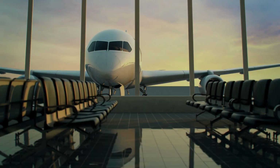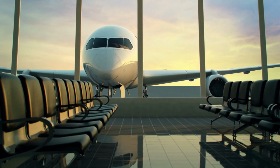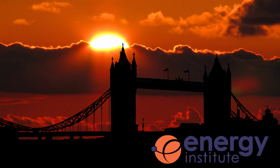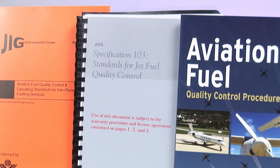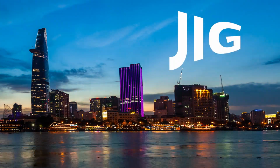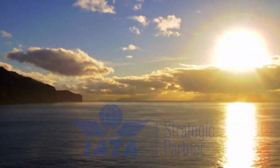The organization that writes the specifications and witnesses the testing of filters, filter separators and monitors used in jet fuel applications is the Energy Institute, London, UK. Aviation fuel handling procedures, including filtration, fall within the guidelines of ATA 103 in the US, and for operations outside the US, JIG, Joint Inspection Group, and IATA, International Air Transport Association.